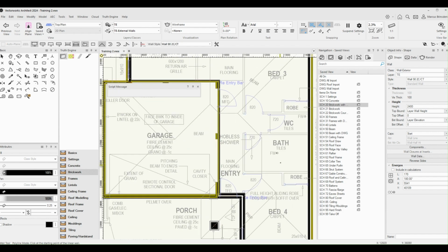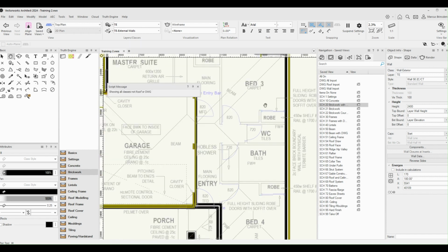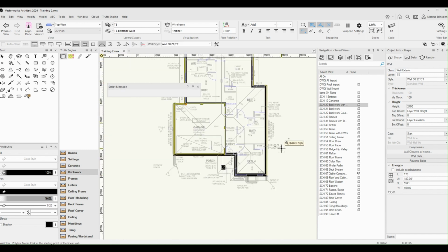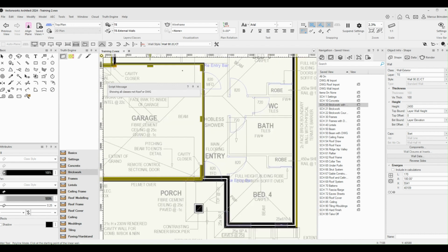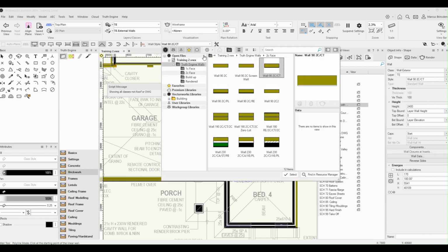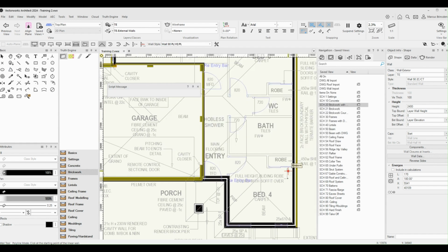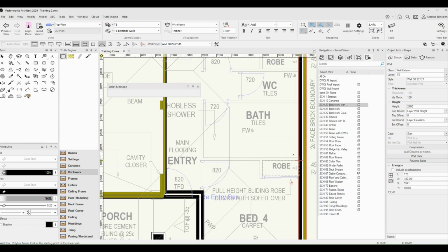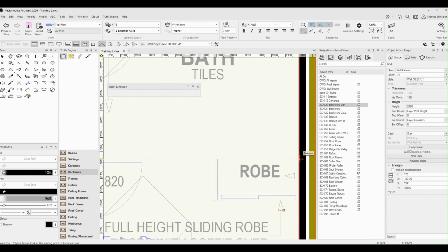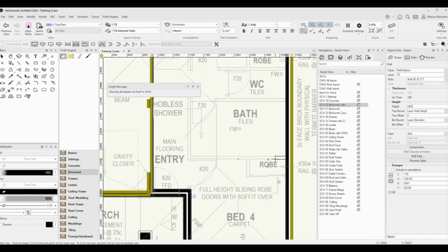Now, next wall I'm going to draw is I'll just show you how to draw one of these internal walls, and then I'll pause the video and finish it off and come back to finish off some of these components out the front. So I'll change it to an internal wall, which is your plaster, vertically cored plaster, and select. And I'll start by just drawing this bath. So I'll just start on one point here. Okay, it's got the alignment right. So if the wall was flipped or on the wrong axis, you can just change it by pressing right control line mode.